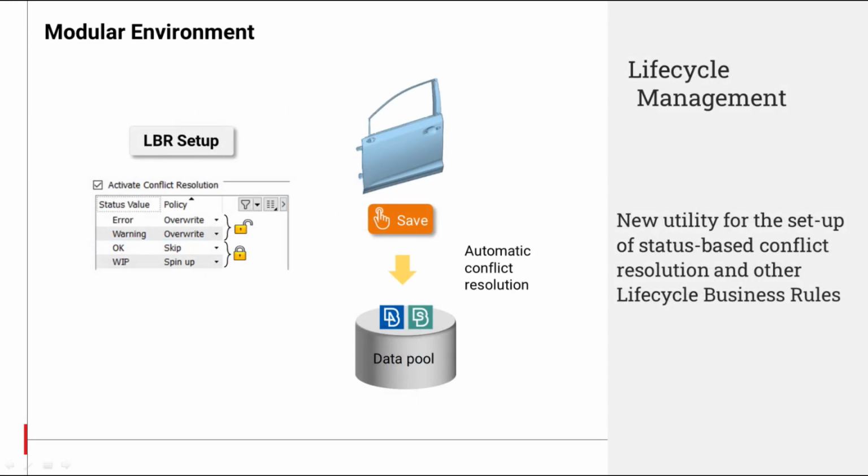Lifecycle management of CAE data is now supported for SPDRM and file-based DMs. A set of rules that govern the evolution of a DM object can be specified for all available data types. These rules are enforced while working with a DM that has lifecycle management activated. Among others, through the lifecycle business rules, it's possible to control accepted transitions of property or attribute values, conflict resolution policy and versioning scheme based on the DM object status and other characteristics, and maturity of DM objects based on the maturity of its references and contents.